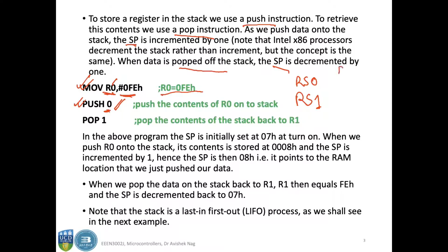This is the MSB and this is the LSB. So if this is 01, then register bank 1 is chosen. If this is 10, then 2, and 11 means register bank 3 is chosen. So depending on these 2 bits, whichever register bank is active, that particular register bank's R0 will be pushed to the stack by this instruction.